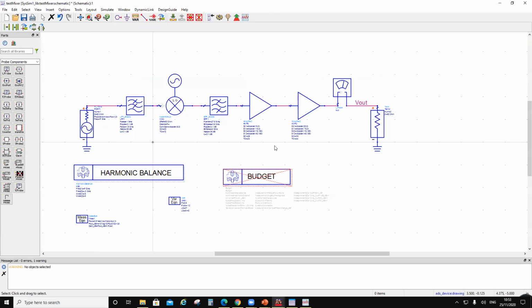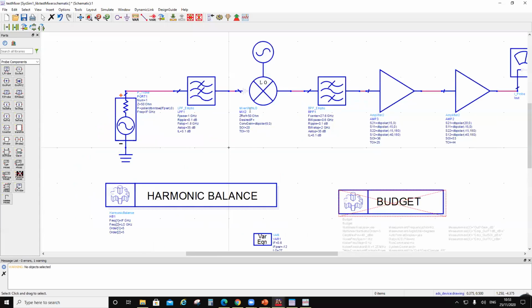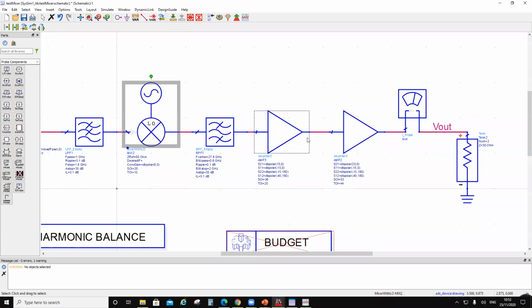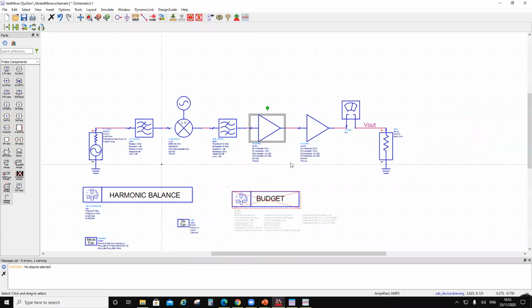Now, once you have frozen a chain, then you can go ahead and start taking these specifications and implementing the circuit level components. What I'm saying is you go from system level, you make sure that you get your delivered power at a given compression, and then you get your specs on each one of them, and then you start doing the circuit design.